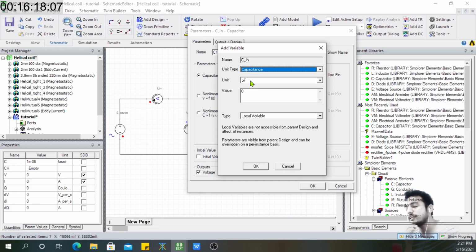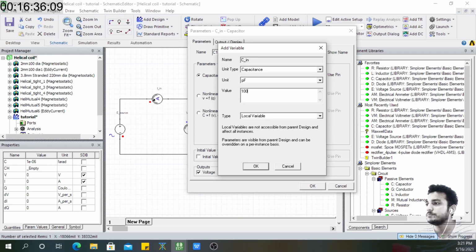It's 15 microhenry, and for 15 microhenry, while you work around with frequencies like 6.78, it is somewhere around picofarad range. So I will just leave it in picofarad, and sometime if you have to change, then you can come here and always change this setting. Okay, so for now I'm giving a random value of 100. This is random. Okay, so let's just do it.